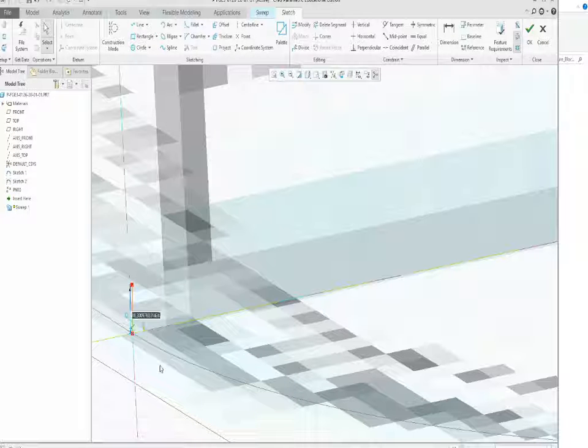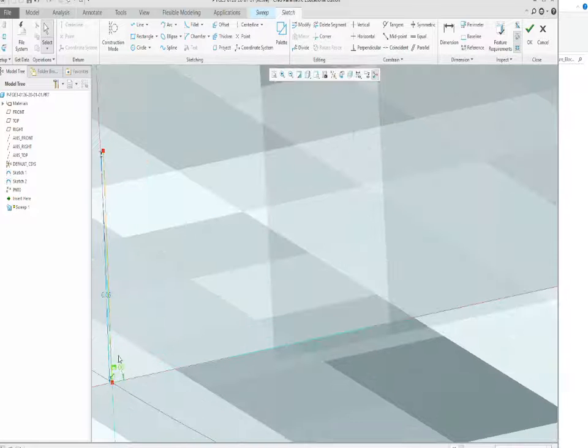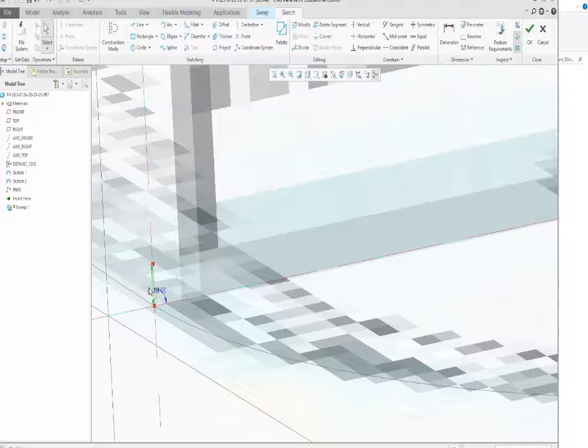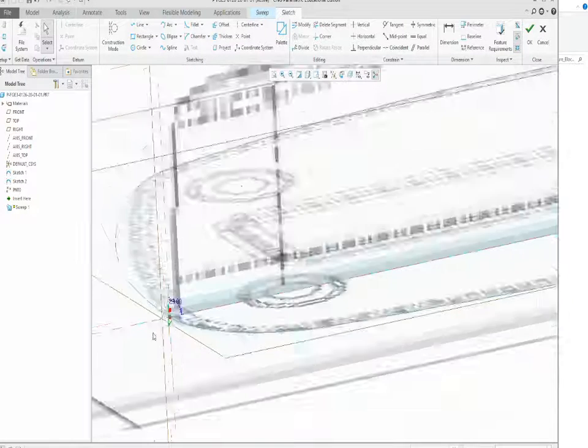So that angle is going to go down to, let's say, 89. So now it's just a tad in, and then we put the length of it up. So this length would be, let's say, about 40 thou. A little bit less. Let's go 30 thou. And that creates a natural rim all the way around the part.